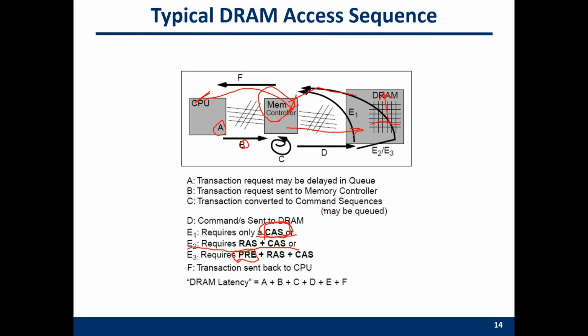The precharge or restore indicates you need to write your content back from the row buffer to the row itself. And then a new row address strobe, and then a new column address strobe. So you have 3 different options. You have the normal option, the standard option, you have the row buffer hit option. You also have a row buffer miss option.